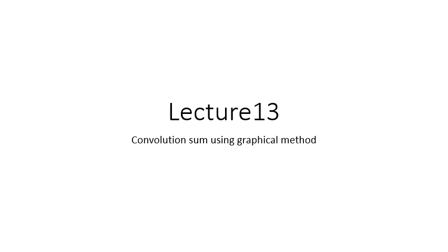In any case, the signal you want to reflect and shift, you should use a separate paper, right? Because in the convolution, we move the signal that is reflected and shifted. So we slide it. If you make it on a separate paper and then slide that paper, it will be very easy for you to find the convolution, right? You can easily know whether we have a non-zero overlap, or a zero overlap, or whether the new interval of the convolution is starting or ending or whatever.